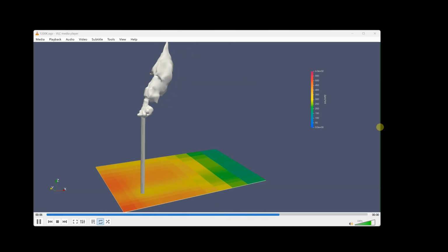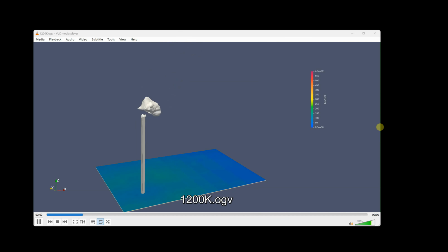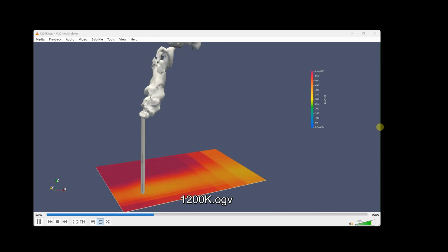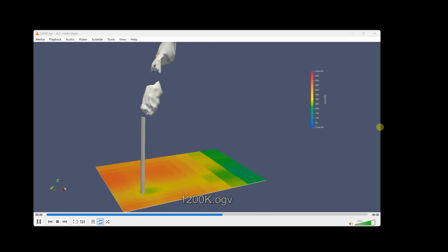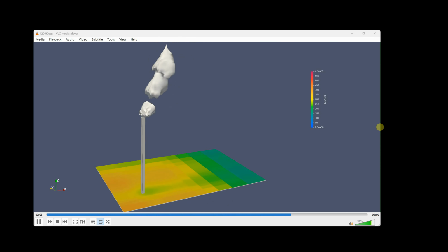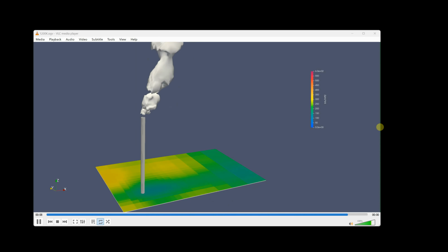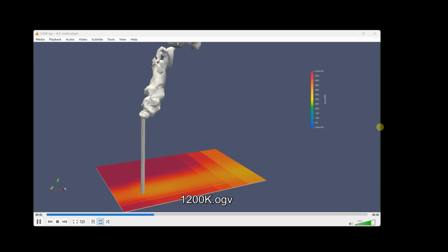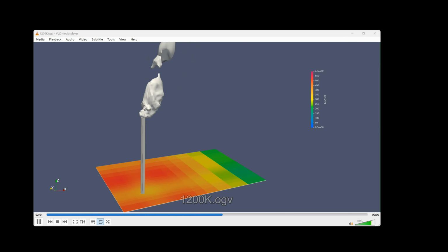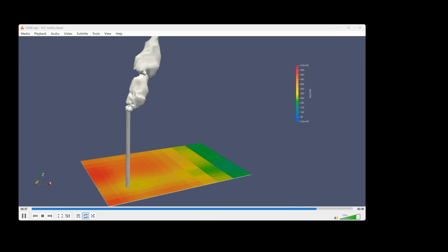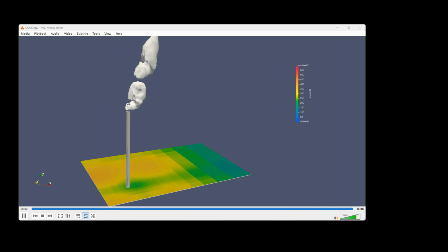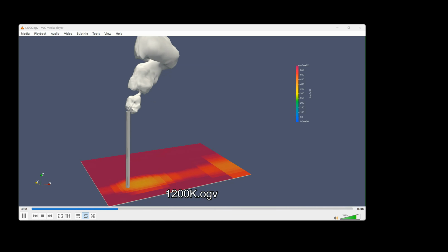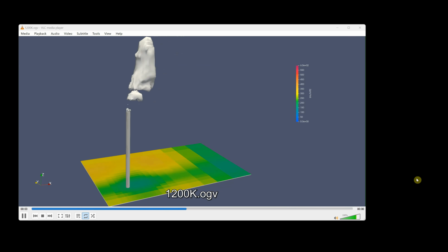And the third one, I'm going to use a group of line sources that you would normally use with a nozzle, and they will be injecting hydrogen gas over a short length. That would be a third method of modeling the flare.